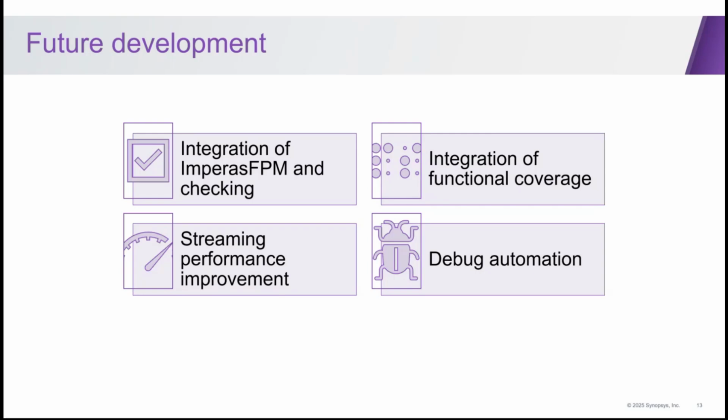Debug automation. I just mentioned the debuggability of Verdi hardware and software. Think about a scenario like this. You are running the regression during your nighttime in the streaming flow. We know your test failed, right? If we can rerun this test immediately, and dump the waveform you specified in case of a failed test, you can dump this trace log and dump the waveform.